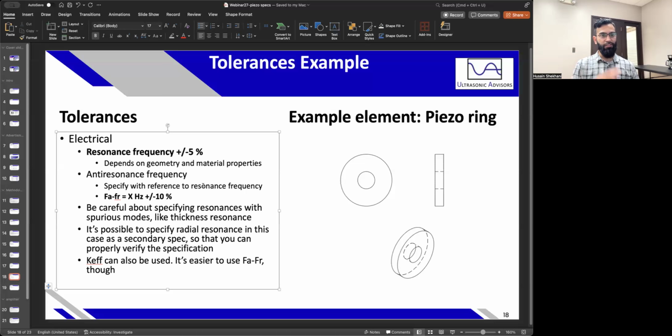So suddenly your device is a fixed 2 megahertz, but you get slightly off. Now your device works a lot differently. Some devices still may work, some may not. So it's something that you have to take ownership of, be aware of, and even maybe save those crystals and materials that are not in your normal specification range,